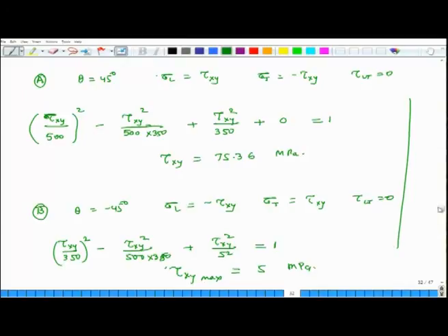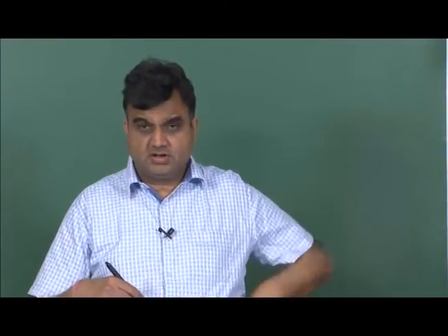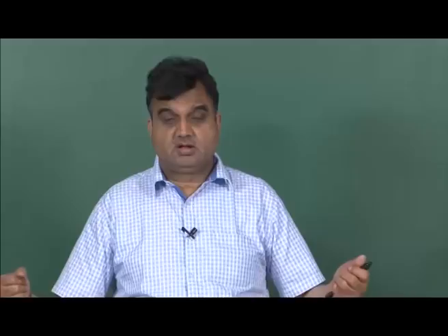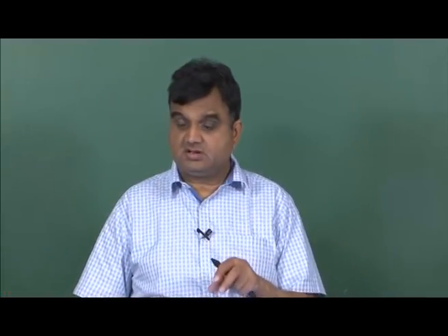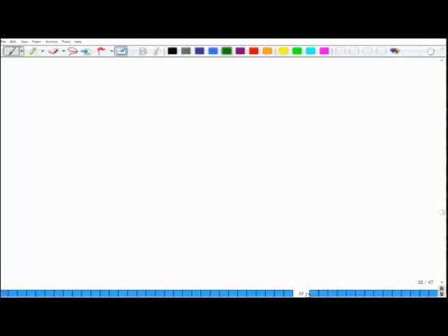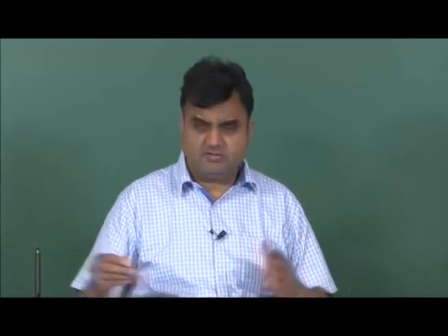So, the point I am trying to make is that just by change of the direction of shear it can have a very significant impact. So, we have to be really careful in understanding the exact direction of shear, because intuitively we understand tension is positive, compression is negative, but a lot of times we do not differentiate the direction of shear. But in this case the direction of shear is extremely important. So, this concludes our discussion for this week, and whatever we have tried to cover, we have covered.